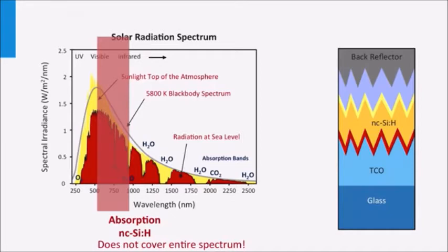Nanocrystalline silicon films are used as intrinsic absorber layer as well in a PIN solar cell. The spectral utilization of the nanocrystalline silicon PIN junction is better in reference to amorphous silicon due to the lower band gap of the nanocrystalline silicon. However, to utilize the spectral part from 700 up to 950 nanometers, thicker films are required. Typical intrinsic film thicknesses are 1 up to 3 microns of nanocrystalline silicon.